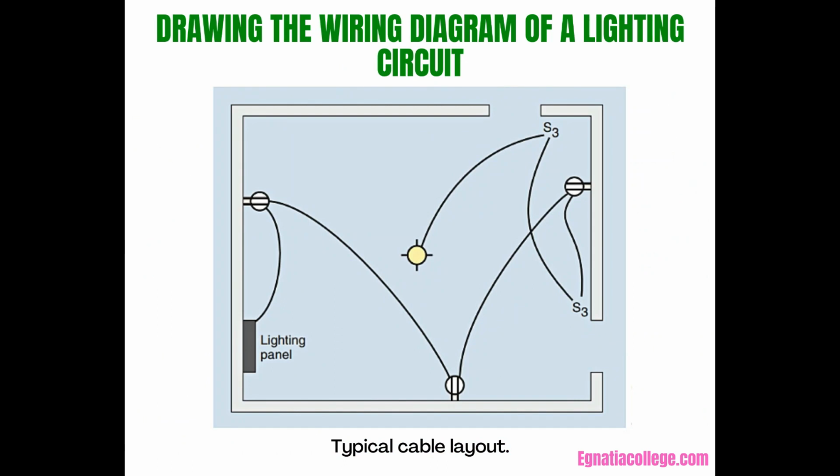The following steps will guide you in preparing wiring diagrams. You will be required to draw wiring diagrams in later units of this textbook. As you work on the wiring diagrams of the many circuits provided in this text, note that the receptacles are positioned exactly as though you were standing in the center of the room. The CEC does not address receptacle orientation on the wall. Many electricians install receptacles with the ground pin on top. This provides for an added measure of safety.